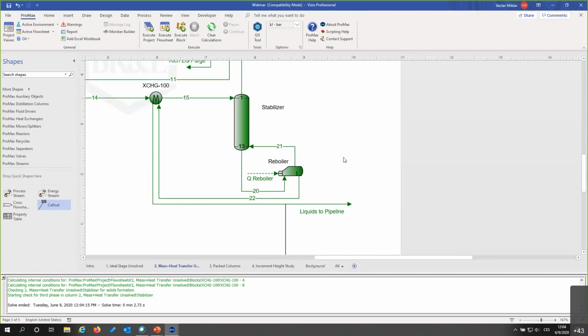And in this case, I actually made a bad assumption. I was too conservative, and I actually used 50% when in reality I would probably end up with a slightly over-designed column. We saw that the sensitivity of the process wasn't too huge, so in this case it wouldn't be a big deal. You always want to have some safety margin.